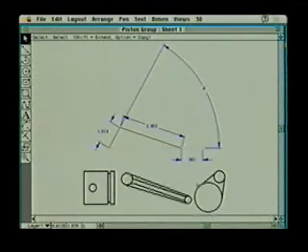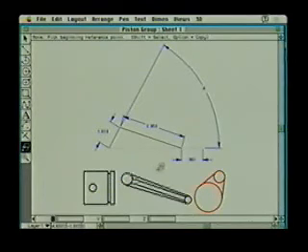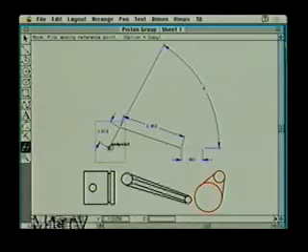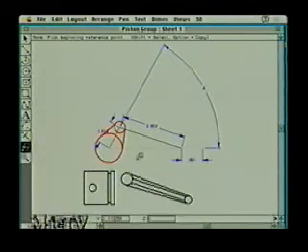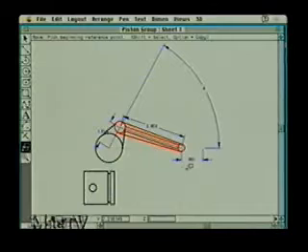Using that kind of functionality, I can undo this and get it back to where it was, and I can associate some grouped geometry or some objects with this. I can pick this part, and with my move tool and with the aid of the drafting assistant, I can grab the center, and I see the word center, and drag it up and place it right on this endpoint. So it's the drafting assistant, that automated intelligence, that helps me do this. Then I can pick this one and not that one, and I do the same thing. I can grab this center, bring it up and put it right on this endpoint. And in the same fashion, I can take this center here and put it right on that endpoint.